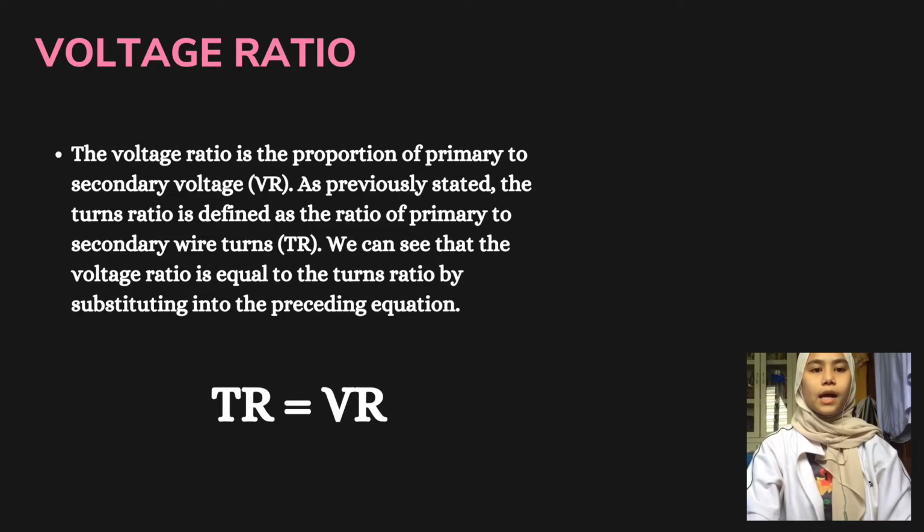volt on the primary. A transformer is referred to as a step-up transformer if the secondary voltage is greater than the primary voltage. The 7/4 ratio means that for every 7 volts on the primary, only 4 volts are present on the secondary. The transformer is called a step-down transformer when the secondary voltage is lower than the primary voltage.